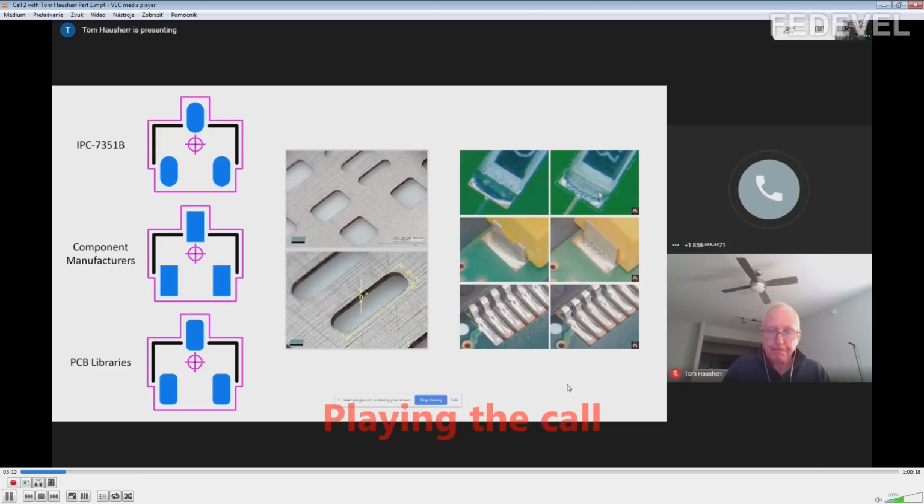I think that when the CAD vendors produced a rounded rectangular pad shape, they kind of made their marketing, this is good for lead-free solder. That's not true. All pad shapes are good for lead-free. There's no such thing as a rounded rectangle that's good for lead-free. The rectangle is good too, and the oblong is good too, and the D-shaped pad shape is good for lead-free too. There's no such thing as a lead-free pad. I wanted to get that out there so that everybody knows that. So it's perfectly fine. Just use rectangular pad shapes, and it's no problem.